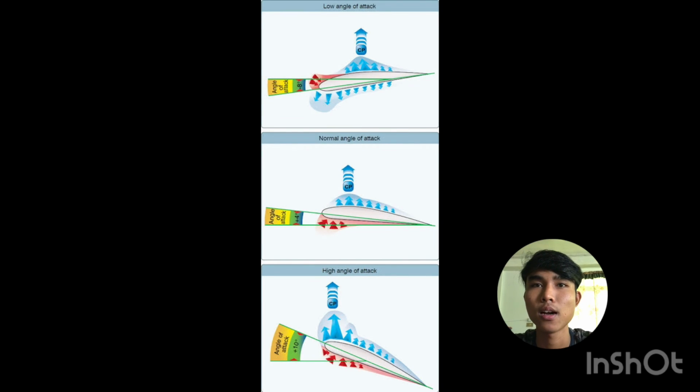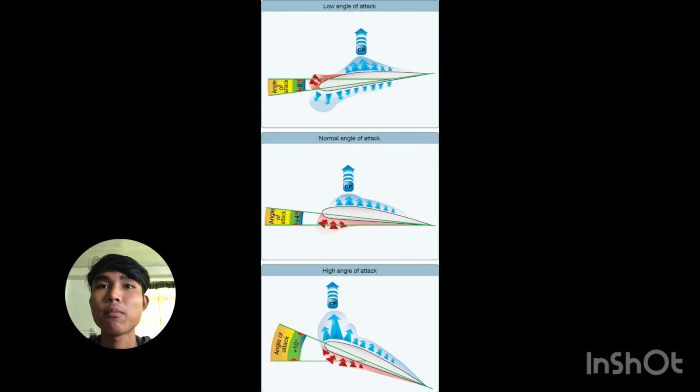Airfoil design. As the airstream strikes the relatively flat lower surface of the wing when inclined at a small angle to its direction of motion, there is a force to rebound downward, causing an upward reaction in positive lift. At the same time, the airstream striking the upper curved section of the leading edge is deflected upward. An airfoil is shaped to cause an action on the air and force air downward, which provides an equal reaction from the air, forcing the airfoil upward.